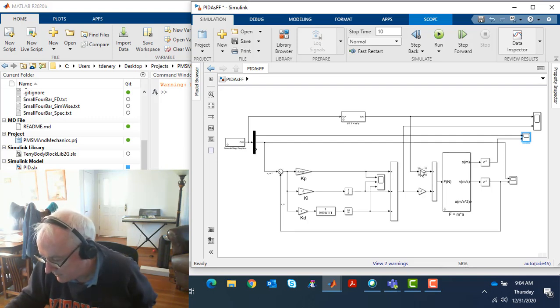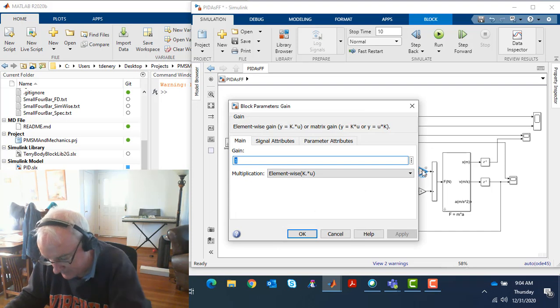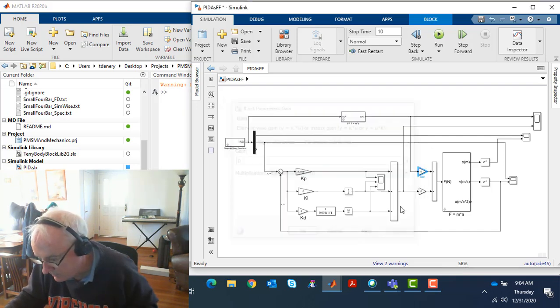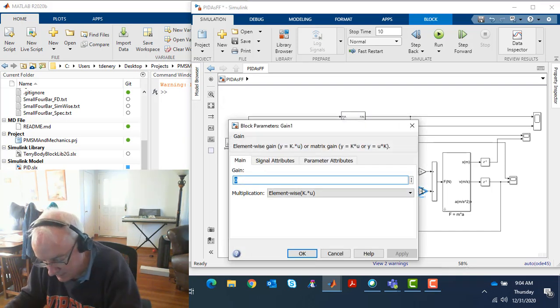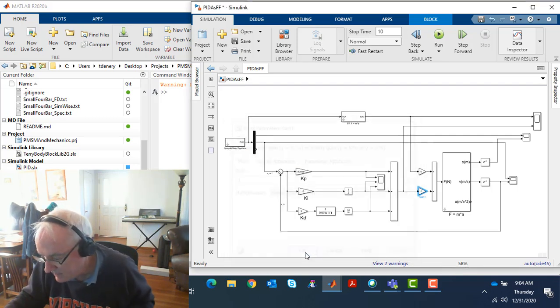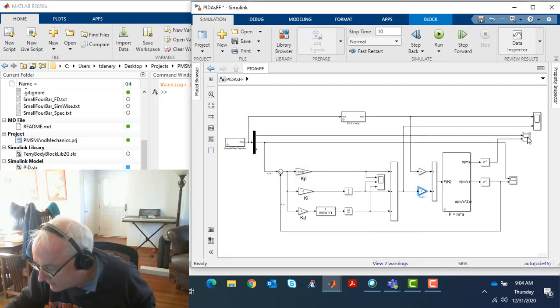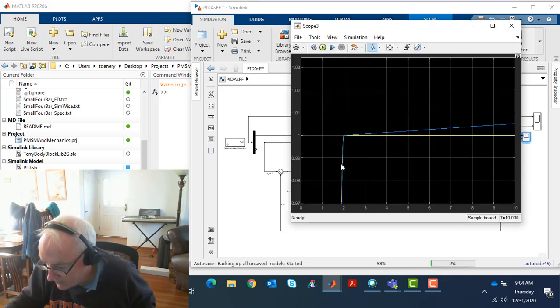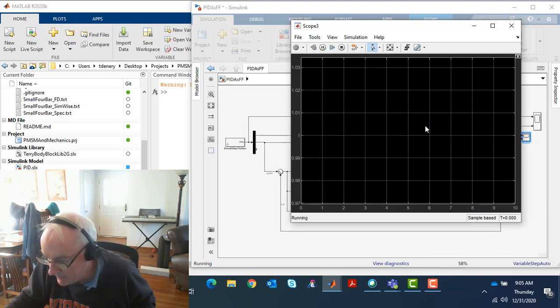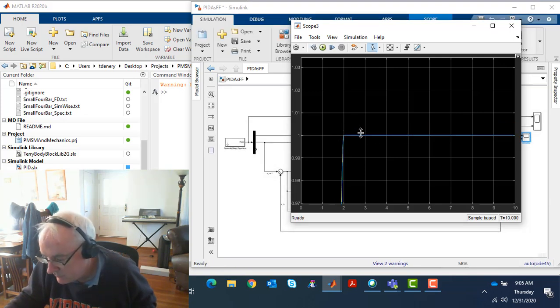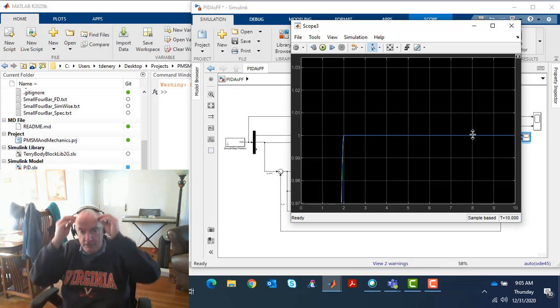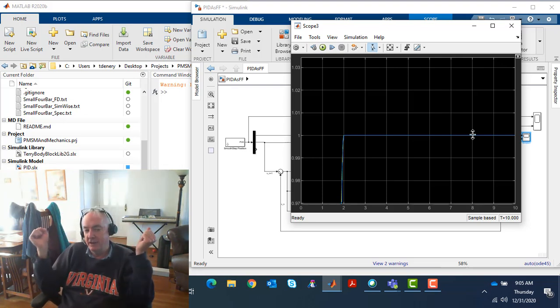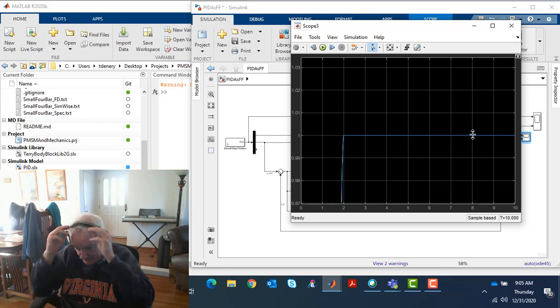All right. And so I'm going to do a few things right now. I want to go 0 on feed forward and 1 on feedback, right? And let's run it again, and I'm going to observe it from the scope this time, with yellow being command and blue being response. And you're going to see what we love about feedback systems is that if there's any error at all, they're really, really good at driving that to 0. Okay, and so with that feedback, we don't get the drift.